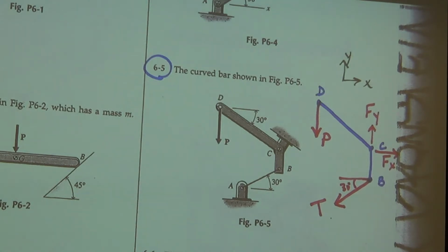Okay? Let's talk about that since the engineering part's the most important, right? Let's say we calculate Fx to be 100 pounds, and let's say we calculate Fy to be 100 pounds. How much do I need to design? What force do I need to design this pin for? Shear force? Yeah, it is a shear force. That's good. I want to know that. What's the number? That's great. Because some of you haven't taken materials, so you might not know it's a shear. But that's exactly what it is.